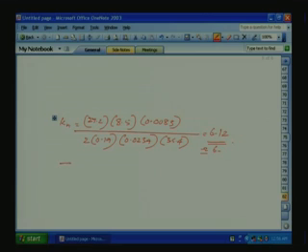Then Tn is equal to 4 into 2 into Tt plus T2 plus T1, which is equal to 140 millisecond. See the assumption: this time constant for the speed loop is much higher than the current control loop. Now, with this we can again design our speed controller.